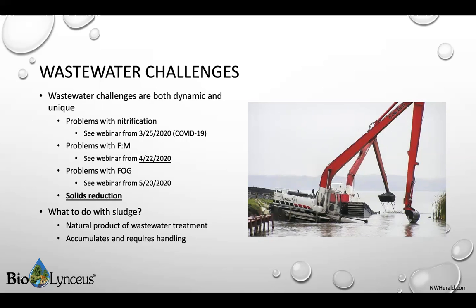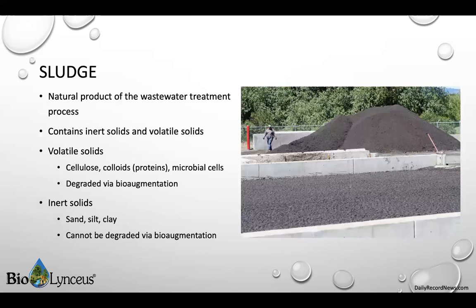Today, I'm going to be talking to you about one of the biggest issues in wastewater today: solids handling, specifically that of sludge reduction. Sludge is a natural byproduct of the wastewater treatment process that accumulates and requires additional processing. Sludge is a slurry of organic and inorganic solids. The organic solids are volatile solids like cellulose and microbial cells. The volatile solids component of sludge can be degraded using bioaugmentation. The inorganic solids are inert solids like sand, silt, clay, and trash and cannot be degraded biologically.